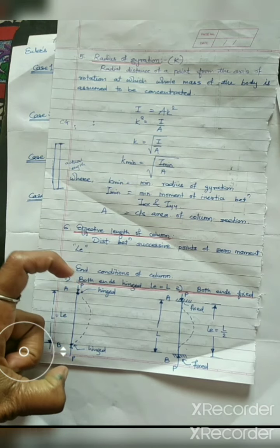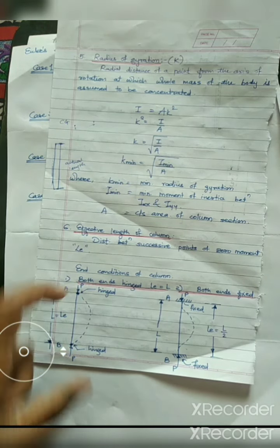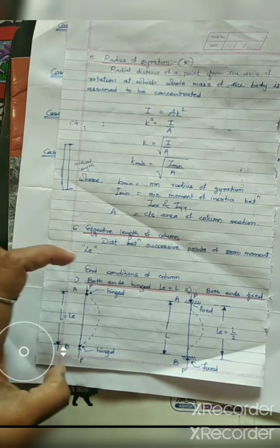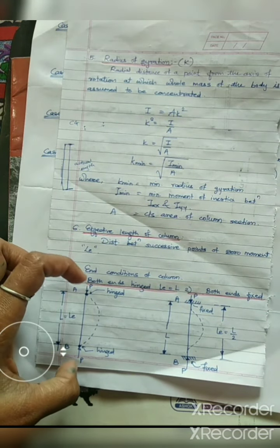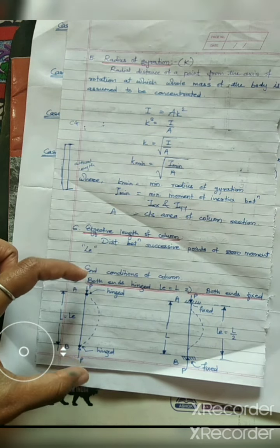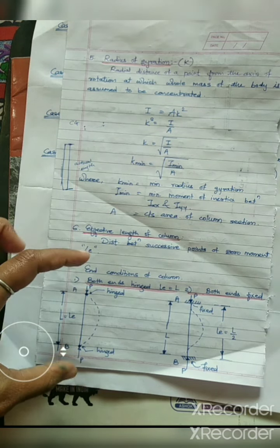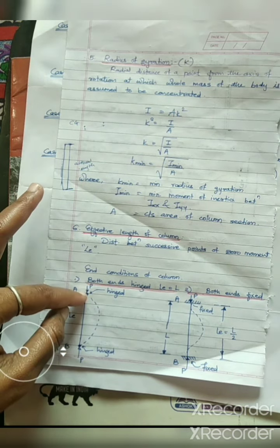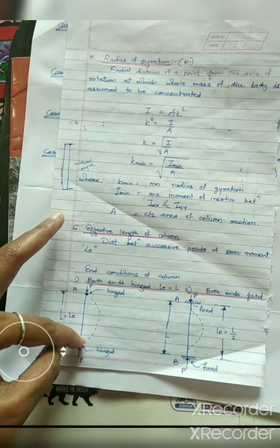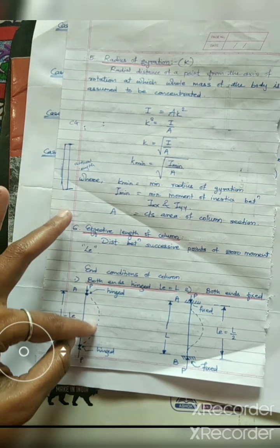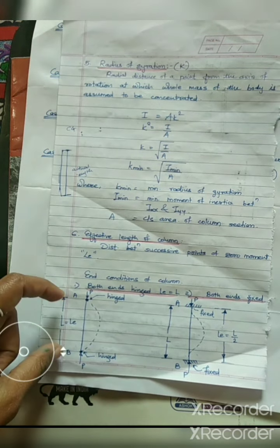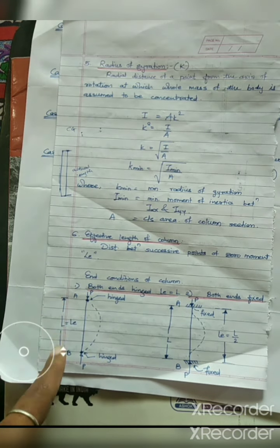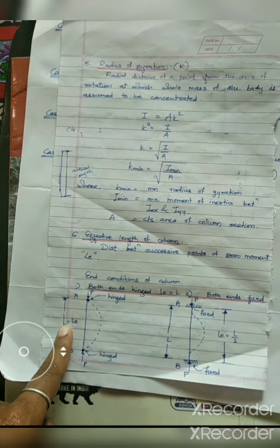You can see the nature of these forces is compressive, because this one acts in the upward direction and this one in the downward direction, and both contribute towards compressive load. If these compressive forces cause the column to bend or buckle in this way, then your effective length of the column will be your actual length.